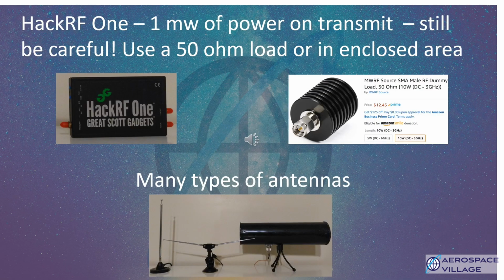We've been talking about SDR receivers. The HackRF1 is a transceiver. It transmits and receives from 0 to 6 gigahertz. That's way above even 5 gigahertz Wi-Fi. Now you have to be very careful. There are legal ramifications for transmitting in a way that would interfere with other signals. The HackRF1 is great for research, transmitting things like key fobs, experimenting in a confined area where you know the signal isn't going to get out.